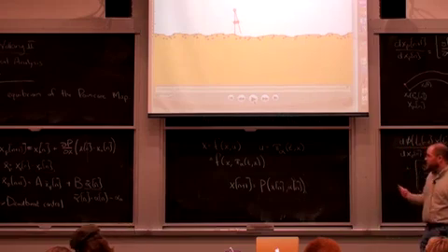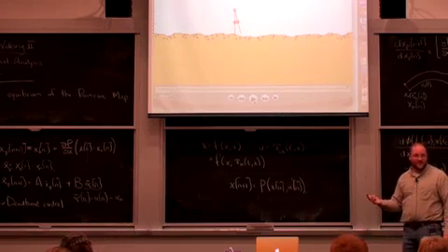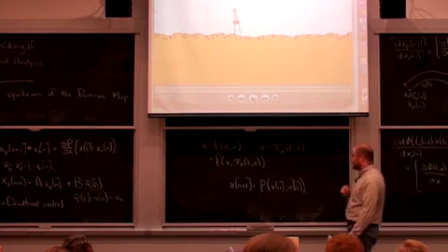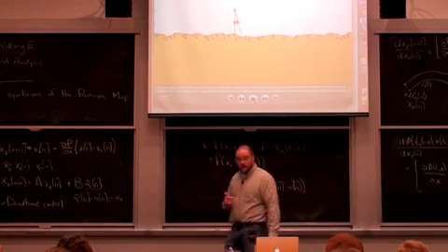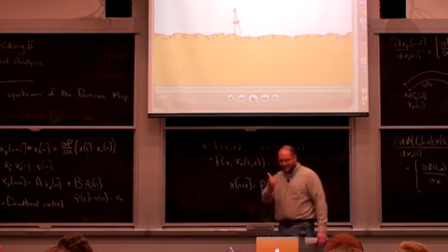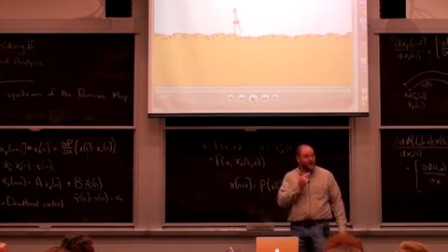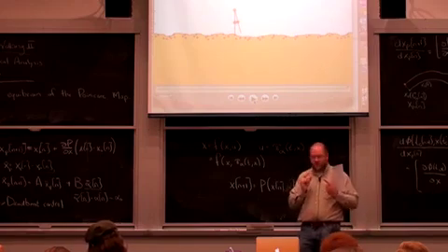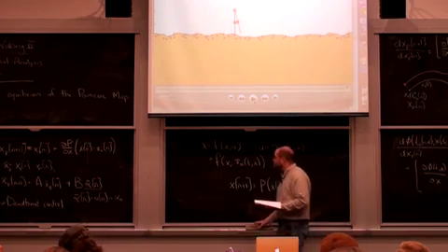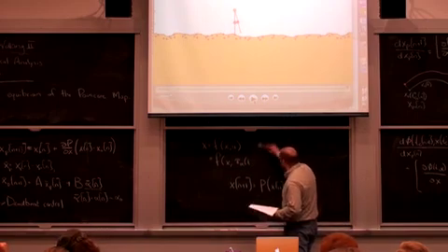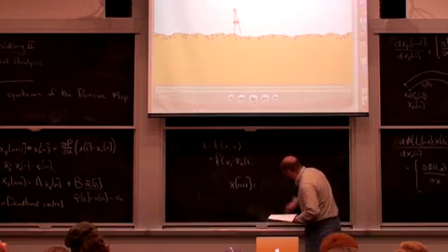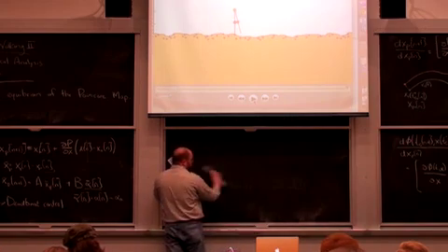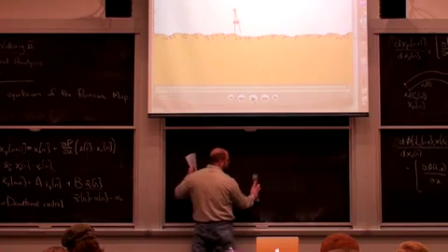More generally, though, we can do control through the swing phase in this case, or between the surfaces of section in a general limit cycle case. If you want to do that, you could do a shooting method. You could do direct collocation, optimize some trajectory. You have to be careful because the time can change during your optimization, the duration of your trajectory, but you could do that. But just like we showed in the acrobot and cart-pole case, people have come up with more problem specific solutions.